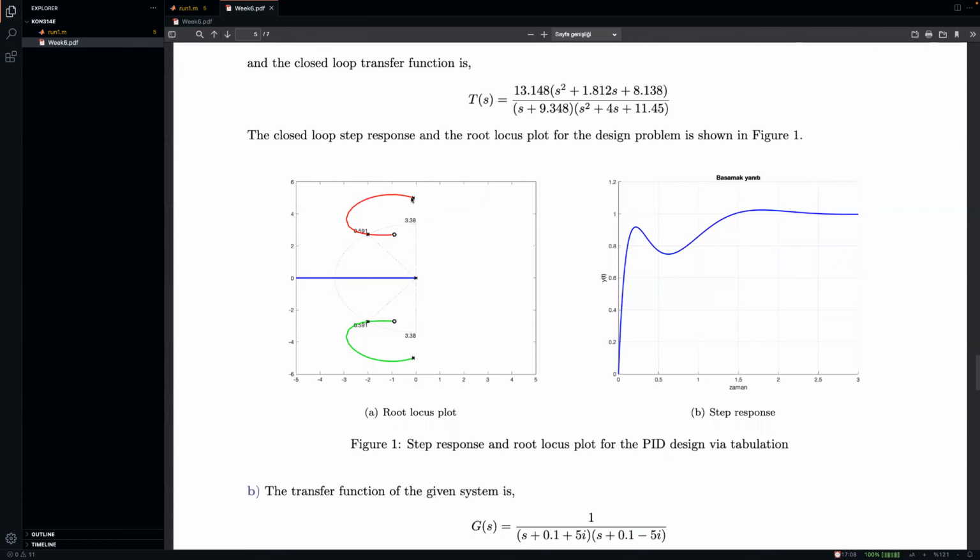This is the root locus, and you cannot avoid having a pole pair and a zero pair near each other that can almost cancel each other out. That's not avoidable for a PID controller. You can see that based on this root locus here. The best you can do, which will of course mess up the settling time of your system, is to increase this gain value so that you match poles and zeros here. But then again, that's not the best idea. Instead, we should maybe place them on top of each other.